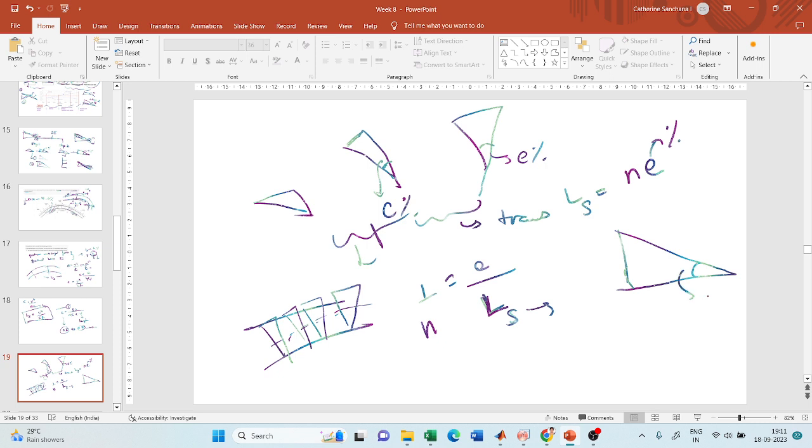So if this is my E percentage and this is my width of the road, based on Pythagoras and trigonometry, you can find out what this H is. It is the rate of change of this H that has to be introduced here. So instead of E, you have to substitute H. It actually has to be H by L only and not E by L. In order to make you understand, I wrote E. It has to be H by L. So this H is nothing but, let us say, tan theta is equal to opposite by adjacent, tan theta or tan E. This E, I'm substituting as theta. So tan theta equals H divided by W.